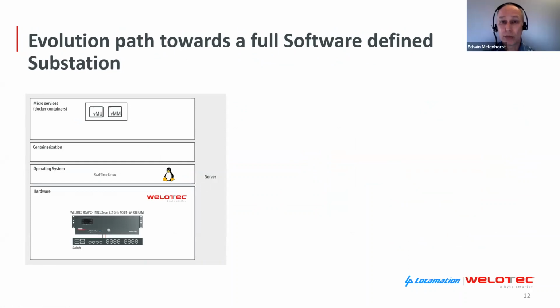So we recognize that installing a process bus, network switches, new IEDs, new way of engineering, and all the other possibilities with IEC 61850 in many cases is just too big a step and currently maybe not necessary or even wanted. This is why we develop our products with a migration path in mind.